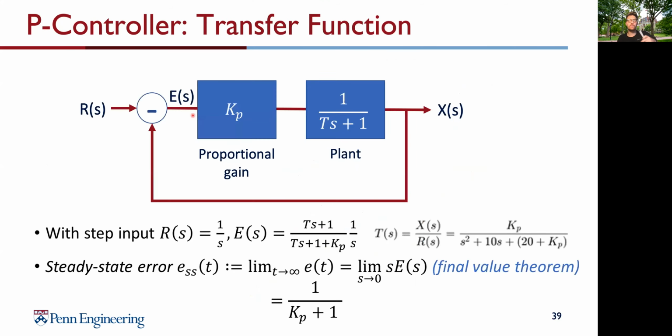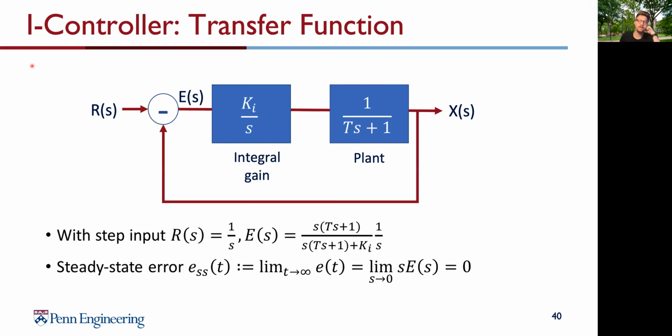And the same we can do for our models, we can do for our controllers. Like displayed here, the PID controller reduces the rise time, increases the overshoot, and reduces the steady state error. The proportional controller in the Laplace domain is no more or less the error multiplied by a factor Kp, which you can see here. The closed loop transfer function of the above system with the proportional controller is then T(s), which you can see down below. And you can do the same with your integral controller.